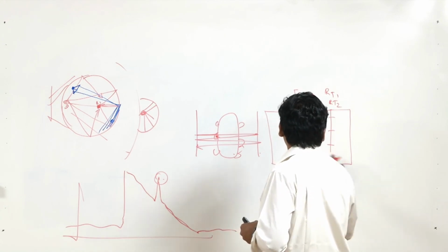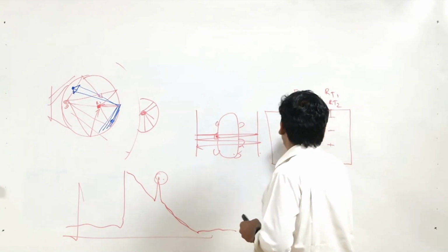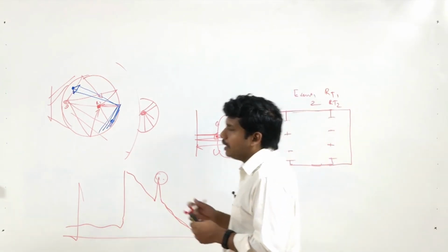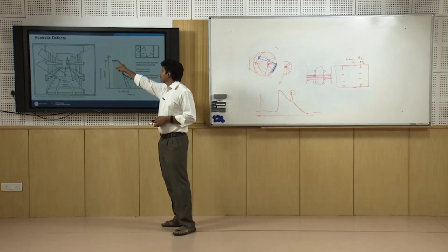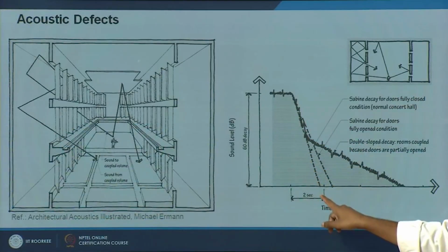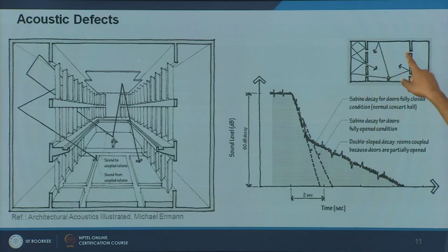In fact, you are trying to increase the volume of the room itself. The whole thing leads to a double acoustical slope, say a double reverberation slope. First is the decay slope, and then there is a second slope. So you have one space, and when you open it up, depending on the volume plus the number of slots you are providing, the slope of decay changes.